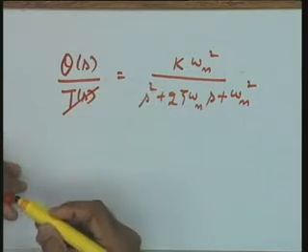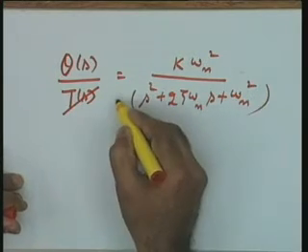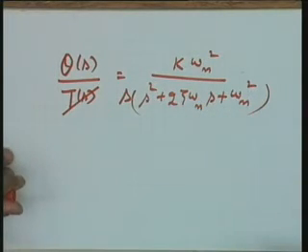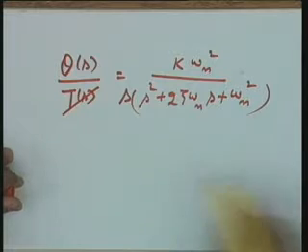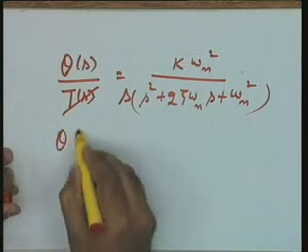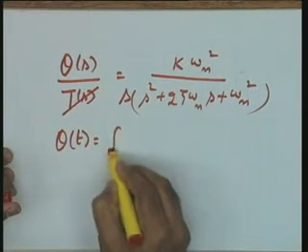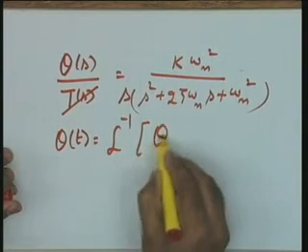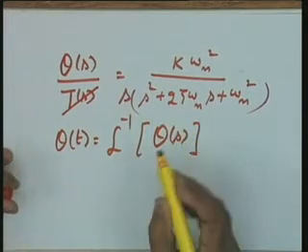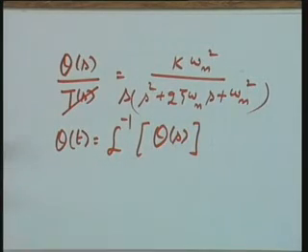Remove T s from here and have the s value here. This becomes your response transform theta s. What you have to do is take theta t equal to Laplace inverse of this theta s. I will be writing the expressions directly. I have taken it in my notes, but you can definitely, for different values of omega n and zeta, take the inverse Laplace transform and verify the expressions of theta t, which I am going to write.